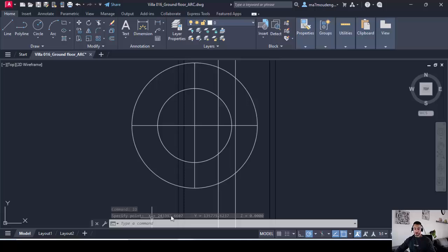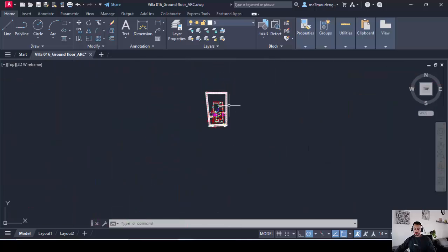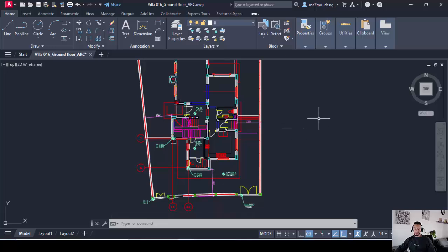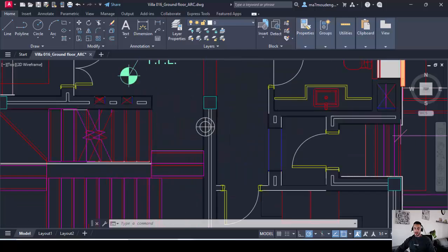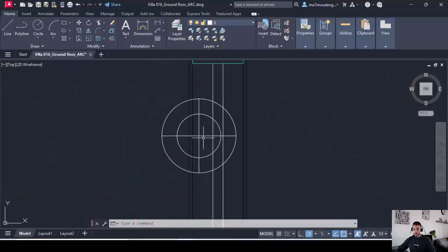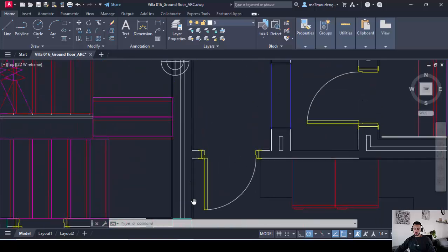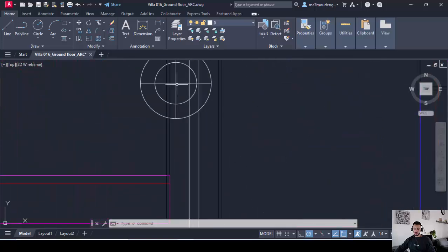What I mean by the correct coordinates, first of all, is that when you are linking with internal origin, the internal origin in AutoCAD is the 0 point actually, which means now we are going to link internal origin to internal origin. You have to move the whole CAD drawing to the 0 point. Like this should be 0 and 0.